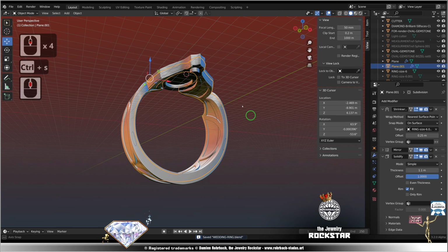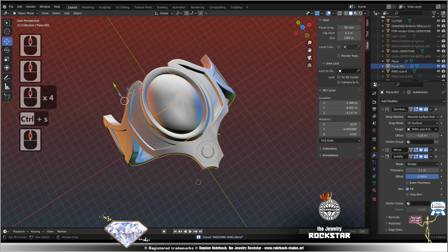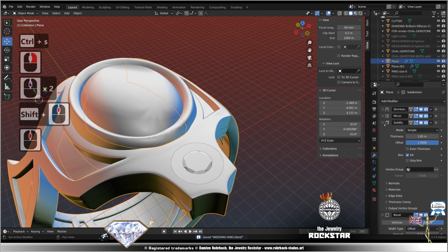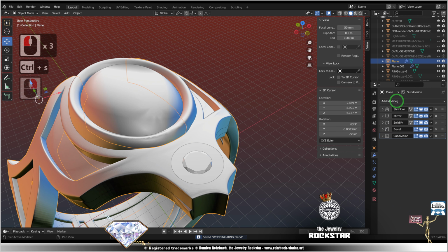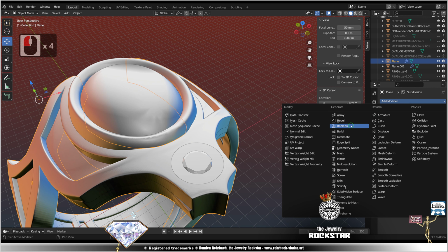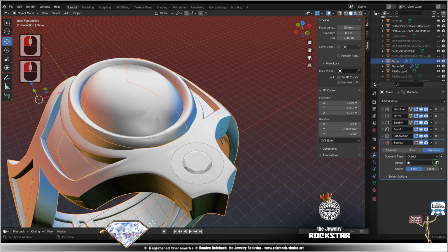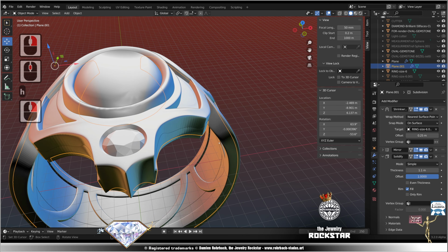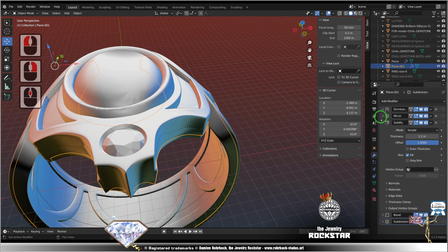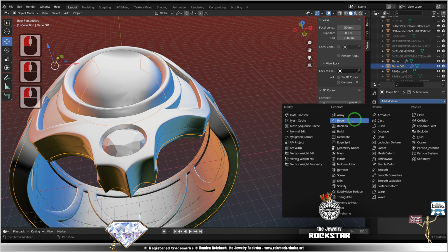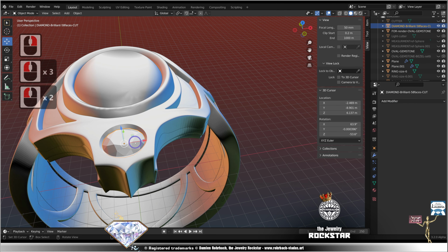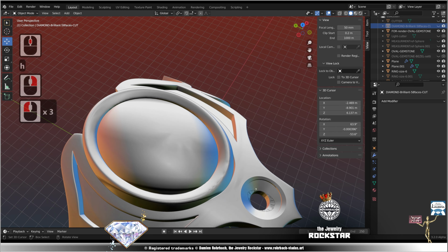I just made an offset on the inside, and I think this is great. Now the only thing that we still need on the edges and on all the meshes interacting with that paste gemstone right there is the boolean. We might have a problem because of the mirror. Let's try. Let's remove the cutter. Let's hide the cutter. It seems to be working. We also need to do that on the solid body, the filler, the inside, boolean, fast, and it's from the cutter. Okay, so let's hide the gemstone here and let's see.